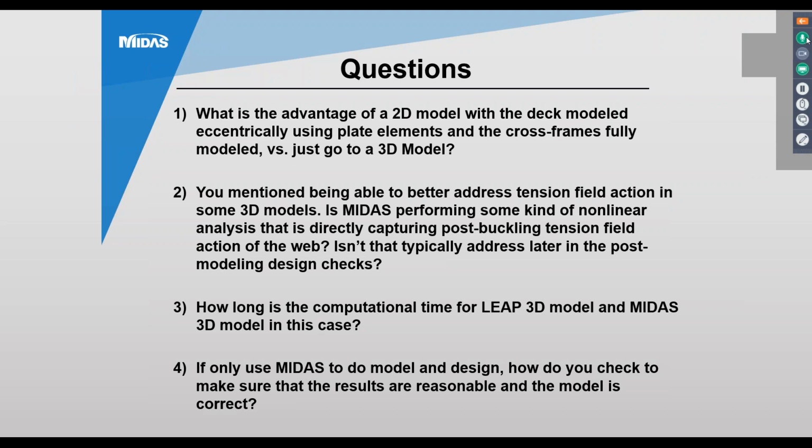So I would say that there is some computational time difference, but not a huge amount, and it's really going to depend on what your input is. And again, I can't really speak to the LEAP 3D as yet. I believe they did just release the patch that will allow that to work. The Grillage and the line girder out of LEAP don't take terribly long, though. You just got to watch that time step or live load step.